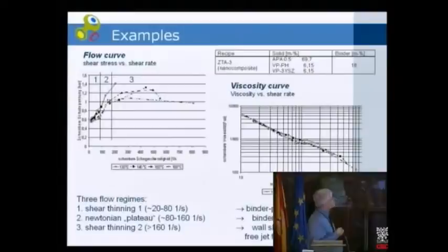And in the third example, this is the same alumina as before, but we have here 10 volume% of nanometric zirconia, and the total mass percentage of solids was 82%. In that case, the microcomposite we had 87, with the submicron we had 85, and here we have to go to 82. So what we can see here is three regions again.